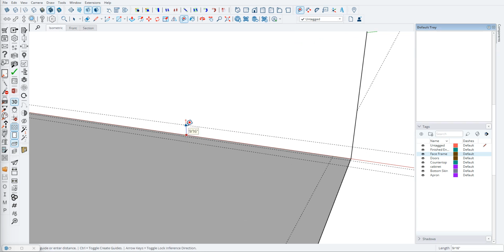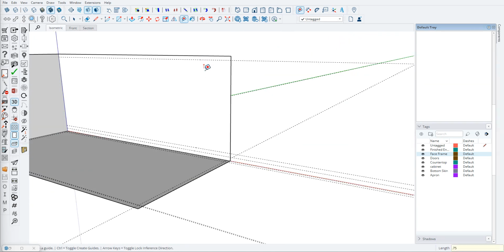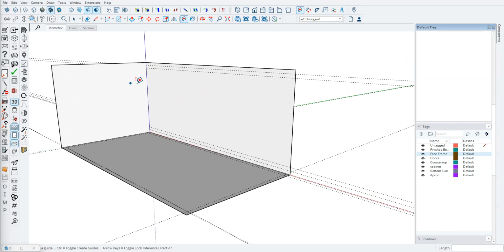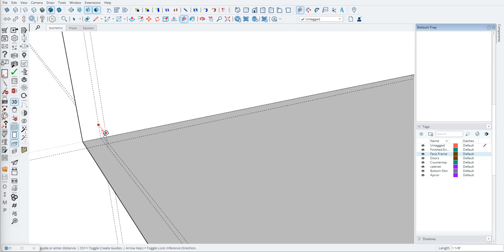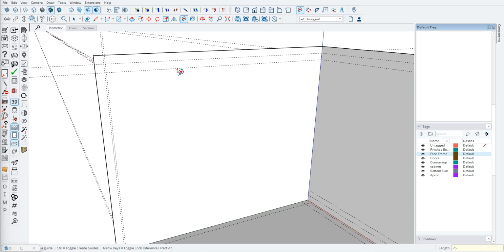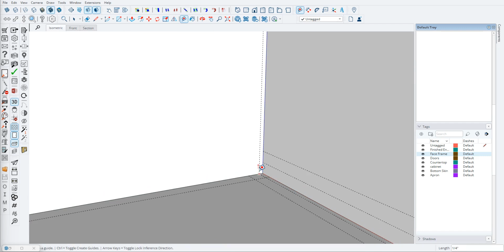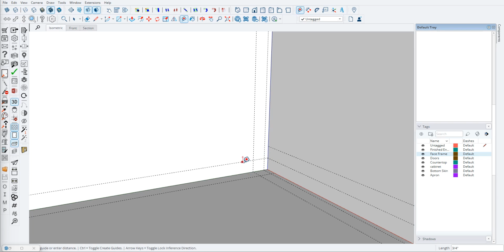So down here, we're going to go up 3/4. We're going to go up again 3/4. The top is going to be a 3/4 countertop, and then we're going to have a 3/4 subtop, which is a cabinet top. And then on this side, we're going to follow the door, and then that right there. Now that's the countertop, and then another 3/4 for the top. So, and then also on this side, we want to capture that and that, and also that.